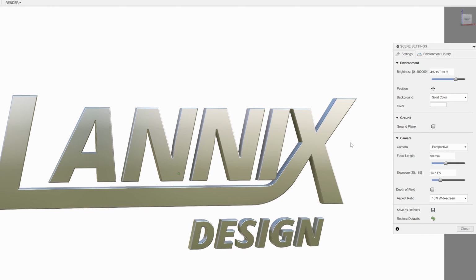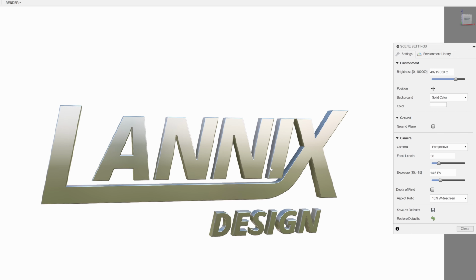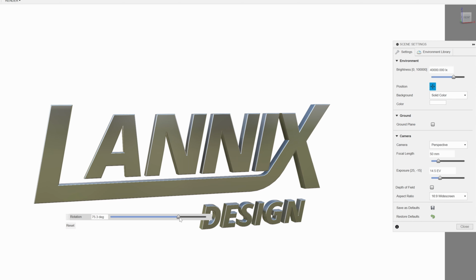Choose a focal length that takes your fancy, play with the numbers to see what you reckon looks best. I'd suggest setting the aspect ratio to be the same as your intended final render. For this job, the 16:9 looks pretty good. You can play around with the brightness settings to find something you like. The position slider will rotate the environment around the model, and it can bring in some different reflections.